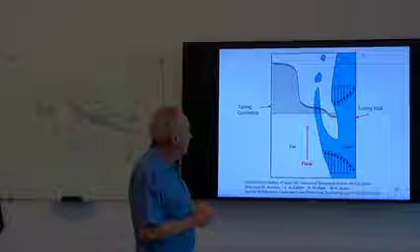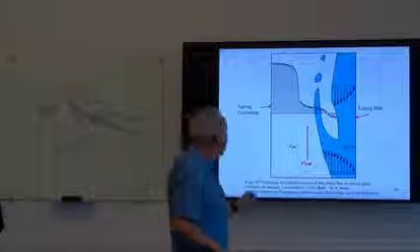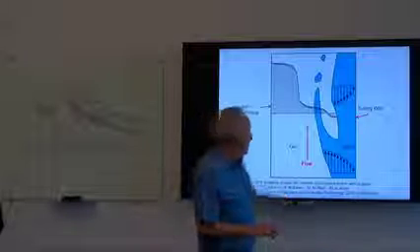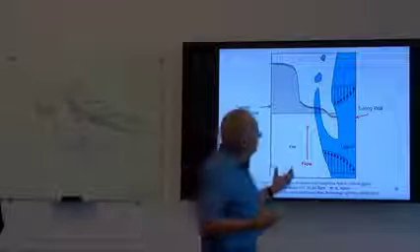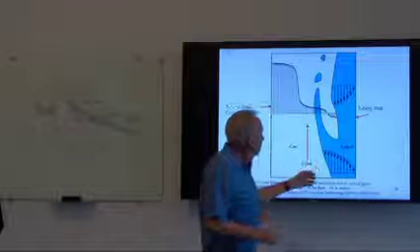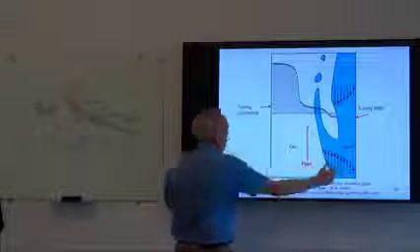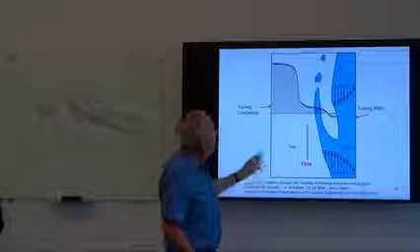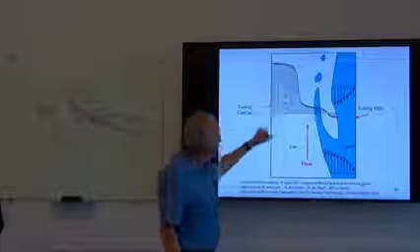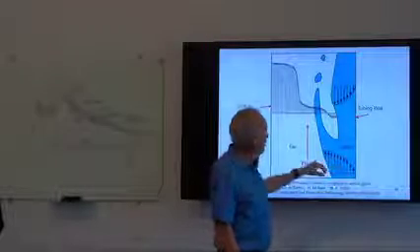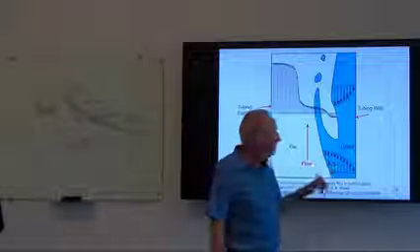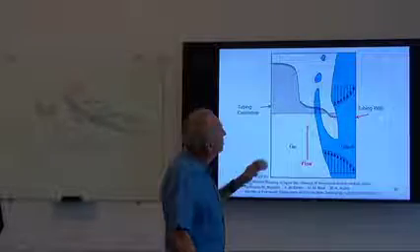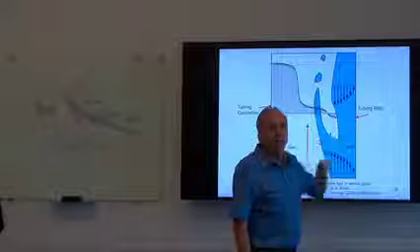This was a study that was done a few years ago, I believe published in the Journal of Petroleum Exploration and Production Technology in 2019. It talks about, if this is a half section, we could mirror this to get the full diameter of the tubing, but we have gas represented by these vectors, and we have liquid represented by these vectors in terms of the velocity and what that liquid is doing, the direction and relative velocity. And we see that we have some liquid reversal.